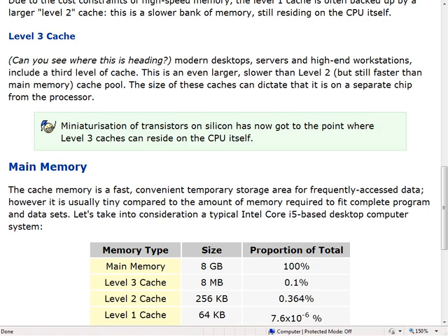The biggest example of this was Intel when they were making the 486 processor. When they first made it, it was a real big challenge for them to make these reliably. At that time, the 486 had two versions, one that had the maths coprocessor inbuilt and one that didn't. The way they binned them is, does the math coprocessor work properly or not? If it doesn't work, we sell it as what's called a 486SX CPU. And the ones that do work, we'll call a 486DX CPU, and we sell it for a lot more and make heaps more money. They ended up making these things so well that they were taking perfectly good 486DX chips and marking them as 486SX, just disabling a perfectly good math coprocessor so they could sell it.